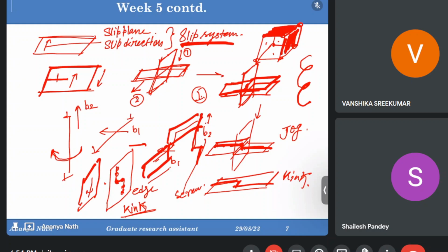So this pile up of the dislocations is also called the forest dislocations, because these dislocations will now create a kind of clusters, and this is what the next topic was. Through the interaction of the dislocations themselves, they will lock each other. So we have seen one technique of strain hardening already, the jogs and kinks.